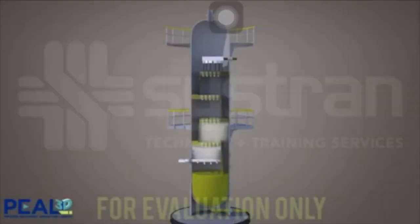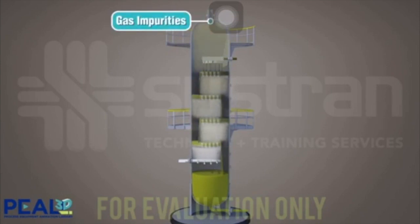As the stripping medium contacts the impure product, the lighter impurities begin to diffuse from the distillate into the stripping medium. The impurities are drawn off through the top nozzle and routed back into the larger fractionator column.